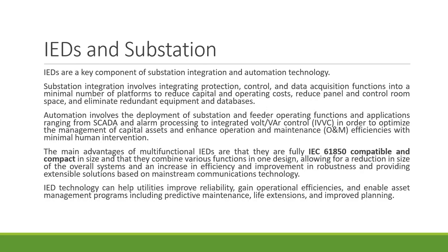Automation involves the deployment of substation and feeder operating functions and applications, ranging from SCADA and alarm processing to integrated reactive volt-ampere control, in order to optimize the management of capital assets and enhance operation and maintenance efficiencies with minimal human intervention. The objective is to reduce error, human error basically.